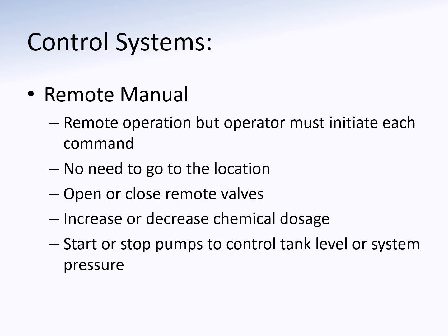So if you can look at several different sites as you're trying to figure out how to manipulate, let's just say, a pump station or a regulating station, you can see the different levels in the reservoir, or see pressures, and make adjustments. So this is the preferred method of control anytime you're operating a SCADA system or a distribution system, excuse me.